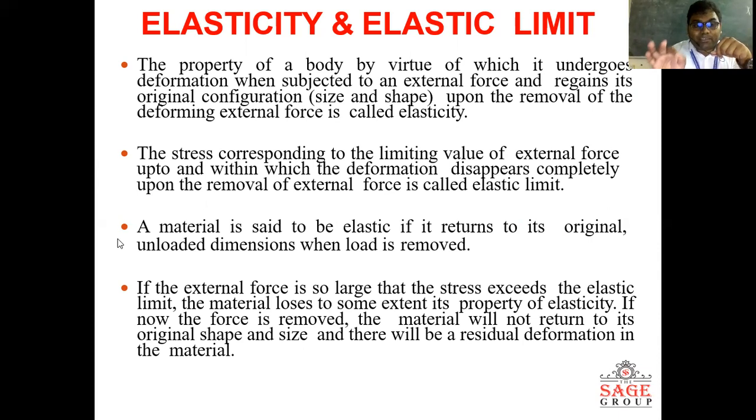So there is a maximum amount of load up to which, if you remove that load, the body is able to regain its original shape. At that limit, the amount of stress set up, corresponding to the limiting value of external force, is called the elastic limit. A material is said to be elastic if it returns to its original position, original shape, unloaded dimension.